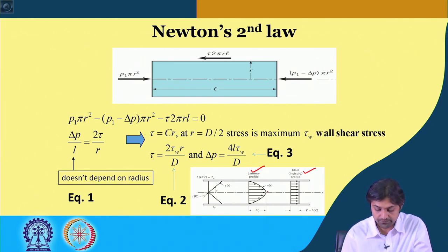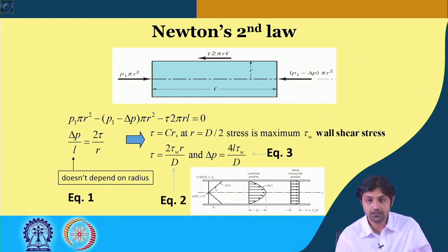You see, this is VC. You remember in our laminar and turbulent fluid flow, we derived that the average was VC by 2, the ideal inviscid profile, whereas it goes from 0 to VC. All right, and the shear stress variation is like this. This is the laminar profile in the pipe flow, and the shear stress distribution is like this. This is something important to remember as well.